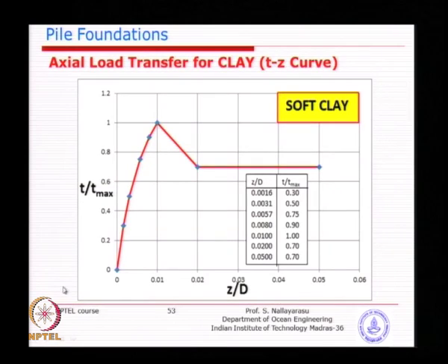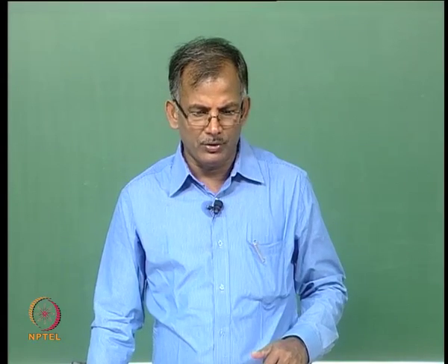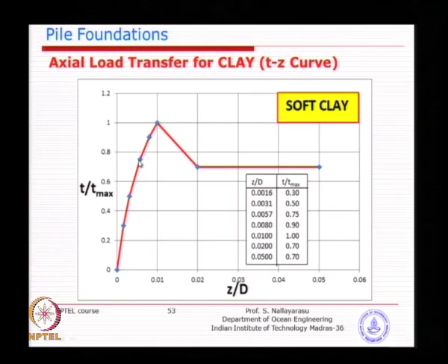The same profile was described by equations of a slightly complex nature, which you will find very difficult to remember. So, API has discretized it, given 4 points. You can just use these 4 points to describe it. In between, you will use a linear relationship, that means from here to here you draw a straight line, which is reasonably acceptable. You are not going to get something big and then come down. So, that is why the linear between the 2 points is okay.